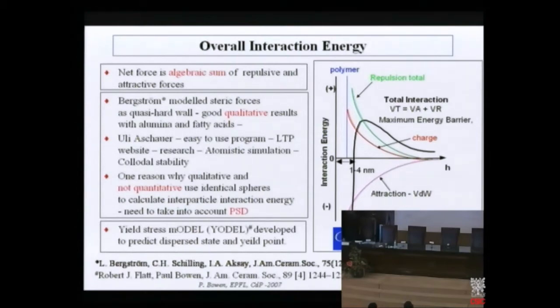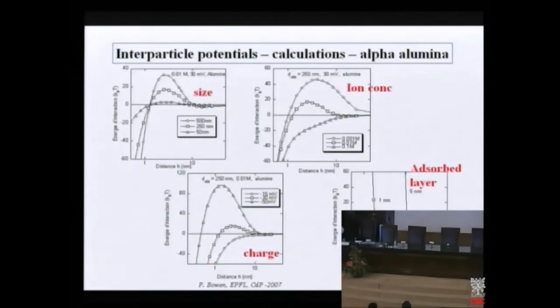So when you're doing tape casting, you have the doctor blade, you have high shear, it's very fluid. Once it's past the doctor blade, you don't want this to run off the edge of the tape, you want it to have something, so under shear, we have something that's shear thinning. So with this type of model, you can work out the shear necessary to make things flow. I won't go into detail today, but it's something we're trying to do to get more quantitative in our predictions with respect to reality, and it works quite well with 1 or 2 limitations.